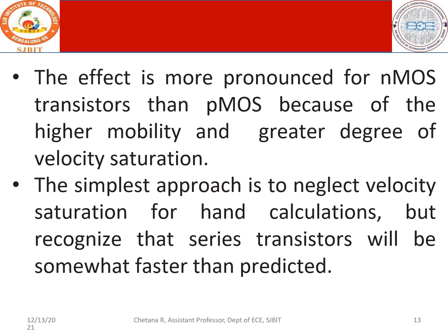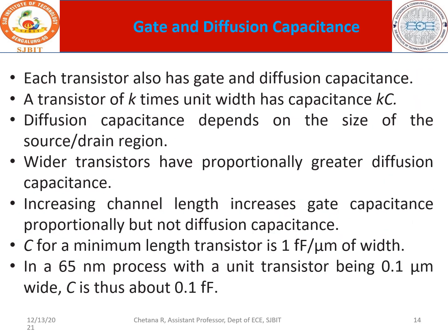Similarly, the effect is more pronounced for NMOS transistors than PMOS transistors because of the higher mobility and greater degree of velocity saturation. So the simplest approach is to neglect velocity saturation for hand calculations, but recognize that series transistors will be somewhat faster than predicted.